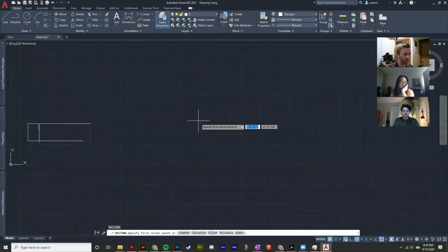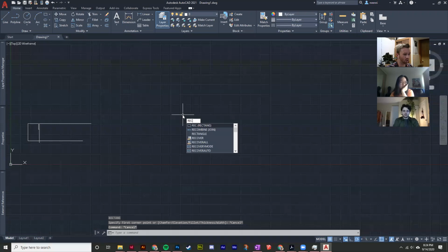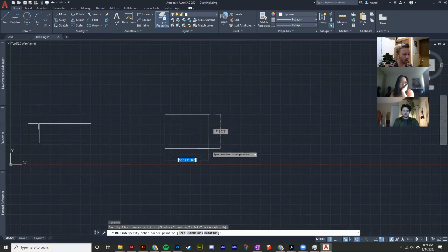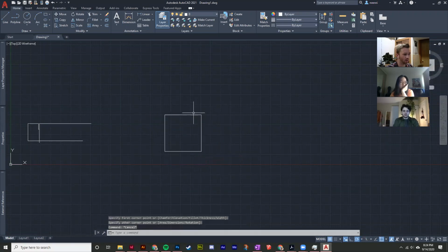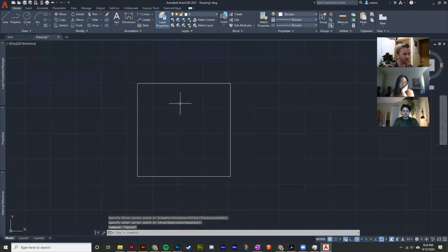Just draw here. Oh, that's another one, REC is short for rectangle, which lets you quickly draw four lines that make up a square or a rectangle. So say this is a room. I just did L, enter for line. We have a wall here.